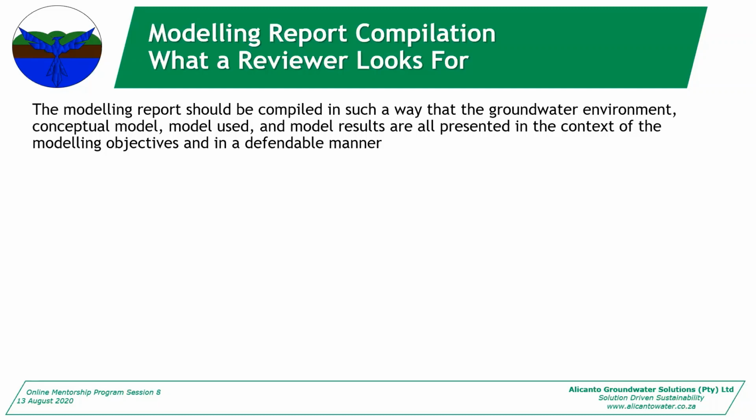The modeling report should be compiled in such a way that the groundwater environment, your conceptual model, the model that you've used, and the model results are all presented in the context of the modeling objectives and in a defendable manner. Remember, you need to defend your model. You need to say why you represented this system with this modeling code, why you chose this number of layers, this grid cell size, these recharge values. Everything should be defendable. If you're doing a dewatering model, you need to say these are realistic because the recharge is realistic, the conductivities are realistic, etc.